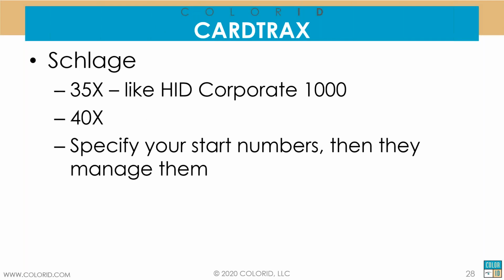Schlage, part of Allegion, offers the CARDTRAX program, which was originally patterned on the Corporate 1000, and their first one was 35X. Surprisingly, 35 bits. If you have a Corporate 1000 facility code and you want to look at another supplier perhaps, if Schlage has your facility code available, then you can get your cards from Schlage in that format. In PROX, in the encrypted cards, not so much. If you want something different and unique, then you can go to their 40X format.